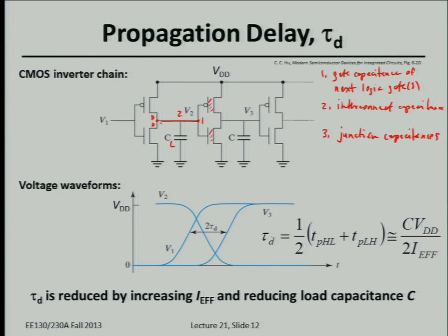Okay, so both the PMOS and NMOS devices have drain to body junctions. They're reverse biased, anyway, but they have small signal capacitance, right? In order to change the voltage on a PN junction, you have to add charge or remove charge. And so it takes time to flow the charges in or to take them out, and that's what adds to the extra delay, right?